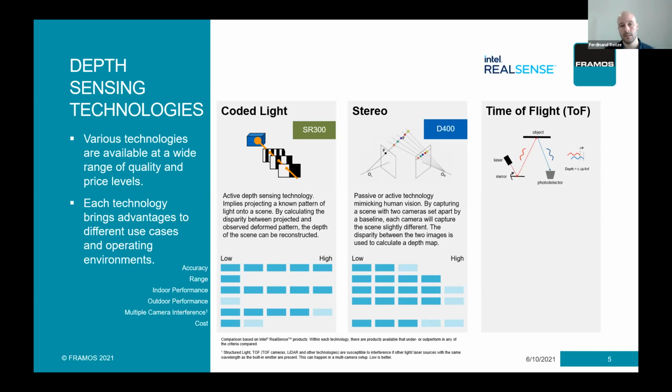That's why usually we talk about active stereo, where you have an additional projector, usually infrared, that adds texture to those homogeneous surfaces that can be used to calculate the depth better. Talking about accuracy, it's usually less accurate than structured light. But depending on the setup, you can also get devices that work in a sub-millimeter space. Obviously, these come at a cost. However, as mentioned, they are very robust when it comes to changing lighting conditions.